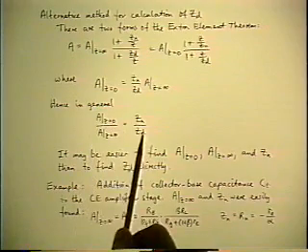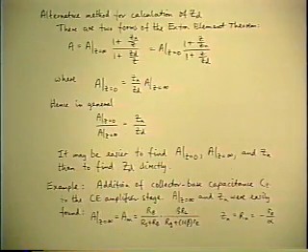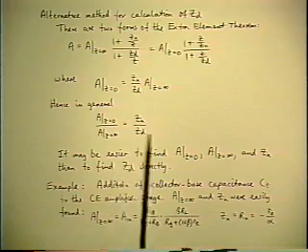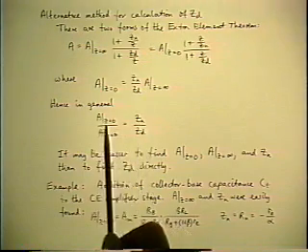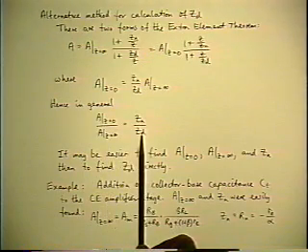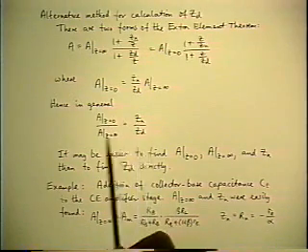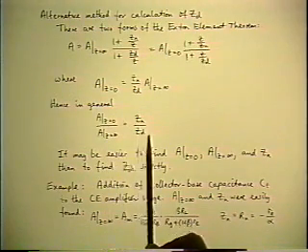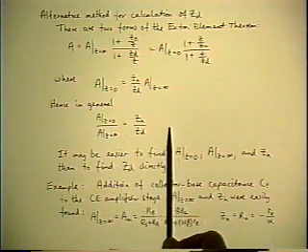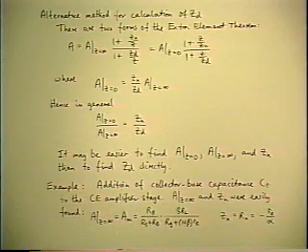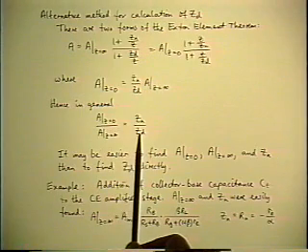And then you can find Zd from this ratio relationship, which would be easy to do because it's only products and quotients involved. So even if you have factored pole-zero forms for all of these, which is desirable anyway, to calculate Zd from the other three simply involves products and quotients of the poles and zeros, and there's no cross-multiplying and refactoring to do. So it would be an easy process also.